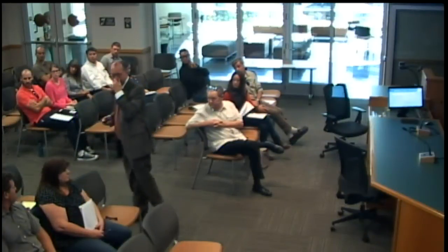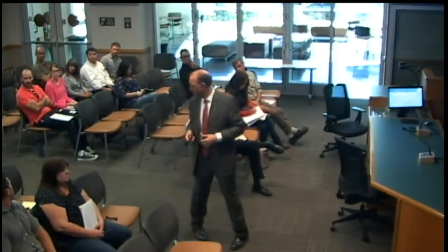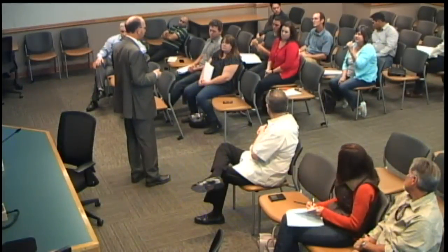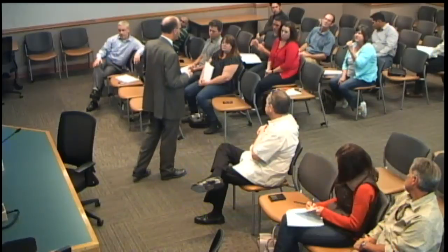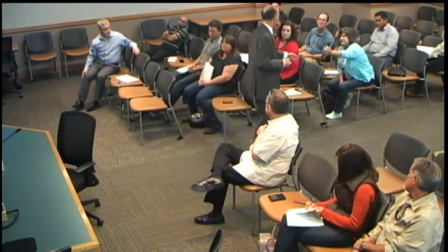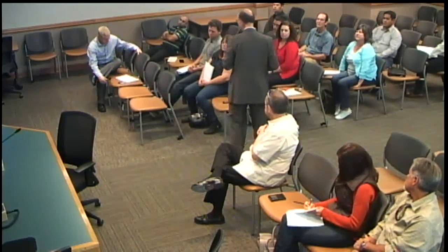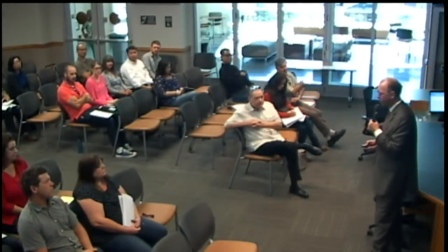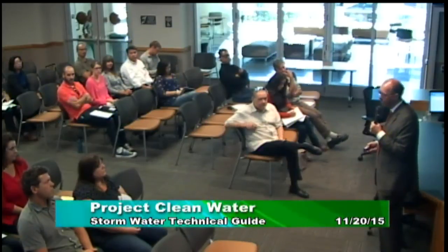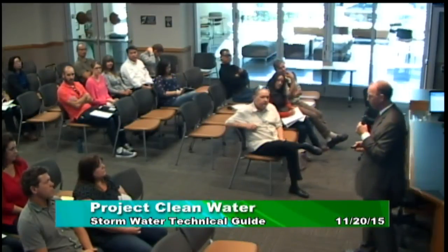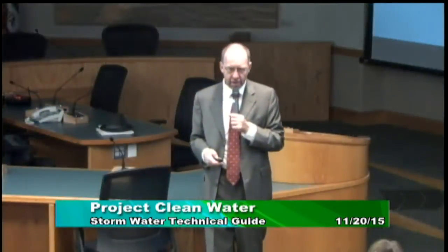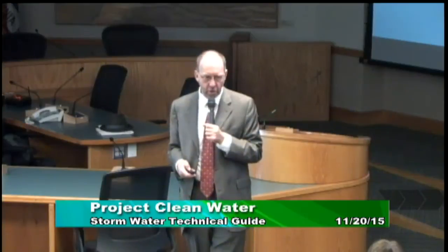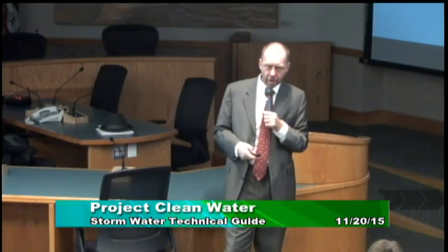Dan, as far as source controls, what are you typically seeing people doing with truck docks? Are they plumbing them to sanitary or to storm drain through pretreatment? Loading docks are one of the toughest because they tend to be depressed, and so they're capturing runoff. And what you do there, I have seen some municipalities actually approve a valve in there, which is then opened when it starts to rain and is otherwise closed, so anything that spills doesn't go down there.